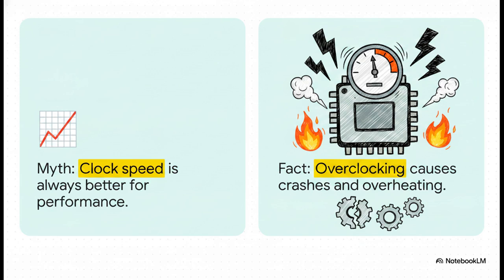Pushing the clock speed past the BIOS design limits, which is a practice known as overclocking, will actually cause unsynchronized operations. Basically, instructions just won't have time to complete before the next one starts, and that leads to frequent crashes, severe instability, and serious overheating of the CPU.